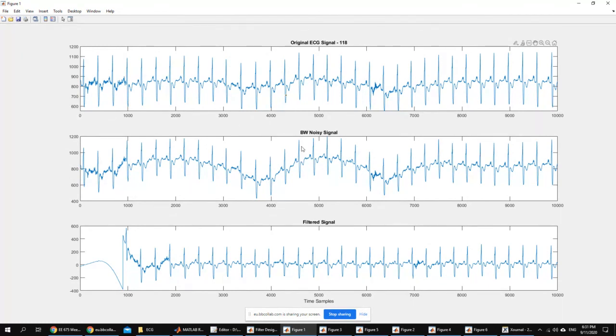If you don't have it, if you have something that looks like this, but you know the ECG shouldn't have these variations, you can still do exactly the same as we did today. You can say that the ECG should be plotted on a flat line here, and we see variations here. I see a peak here, a peak here, a valley here, a valley here. So I can estimate the baseline wander frequency based on the variations of the actual signal, even if I have only the noisy signal. But since the database already had the original signal, we looked at the artifact right away.